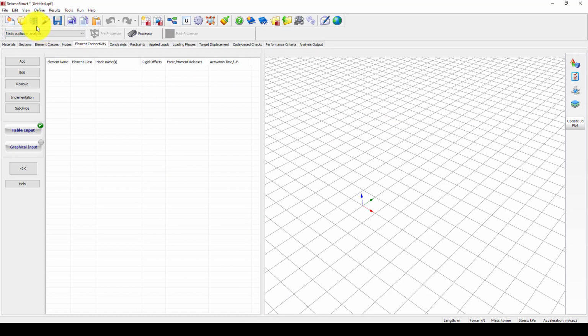Because in some areas, instead of this infill panel, we can add the load to the beams. So we do not ignore this. We can come to the geometry and select the proper beam, 400 by 500, and here select the middle point, and I'm going to select to here, to here.